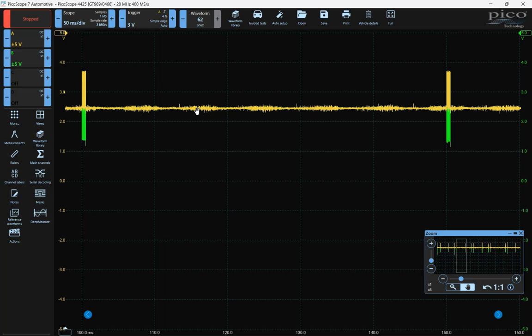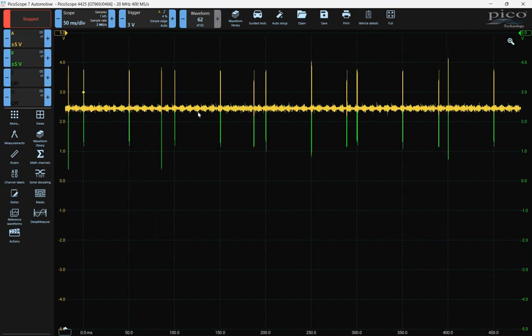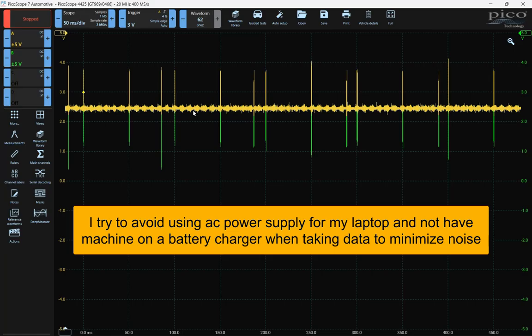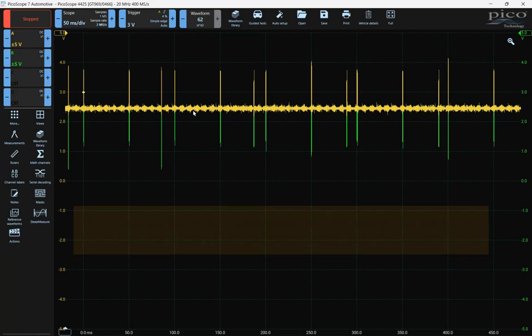A lot of this is because I'm powering this off of a DC power supply, so it's connected to the AC 120 volts, 60 hertz. So some of this is the noise, if you would, from the power supplies. My computer is also sharing that same ground. So sometimes when we do these bench setups where we're using something like the real devices.